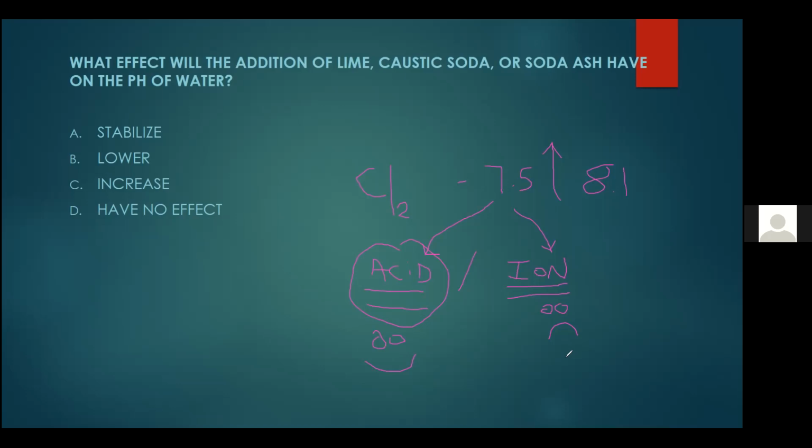They had an issue here that my pH was almost 8 coming in, and the product we're using for coagulation was working at best at 7.8 pH. So we weren't getting very effective color removal. So always be aware of what your pH is and how you can adjust it if you need to.